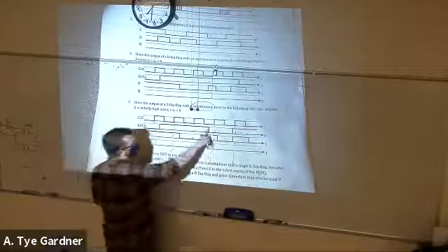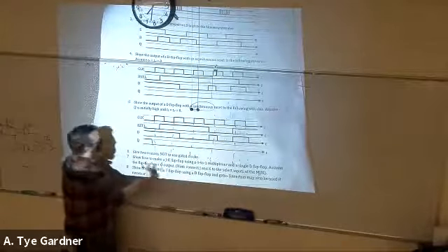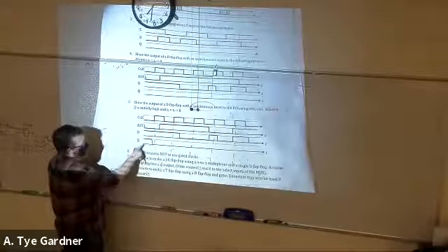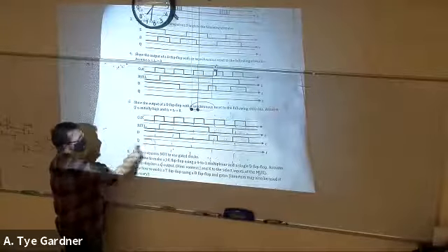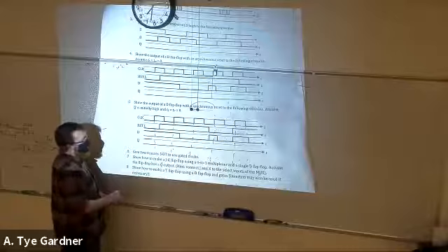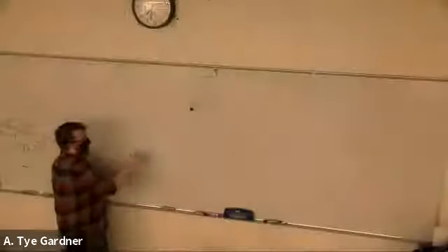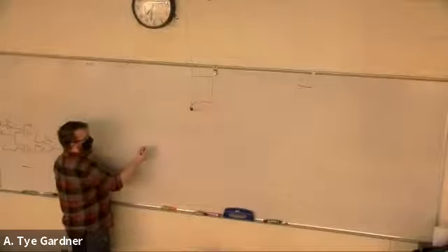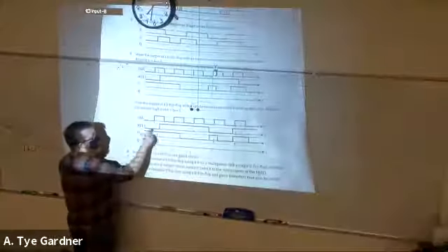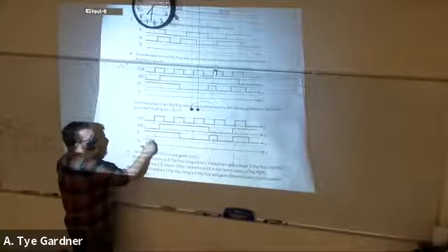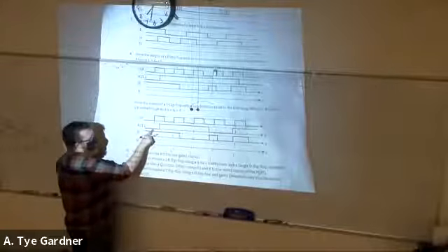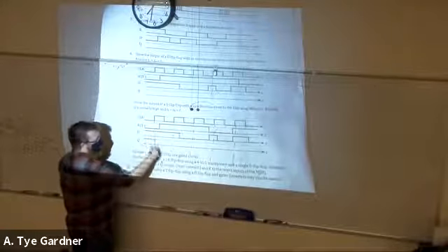All right, so it can't even change here. So I guess I'm mistaken because I thought it was asynchronous reset. It doesn't fall low. My apologies. It can, however, fall low here because we're synchronous. Clock hits, is reset, drops low.